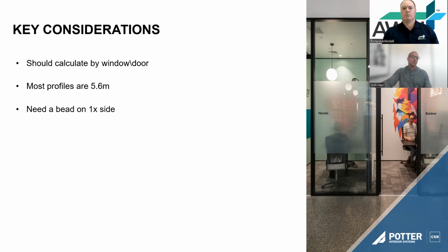Sometimes designers don't design partitions to have a bead, and you do need to allow for a bead on one side, ideally the bottom. So just think about that. If you're doing a takeoff based on plans, allow for a bead on the bottom at least.